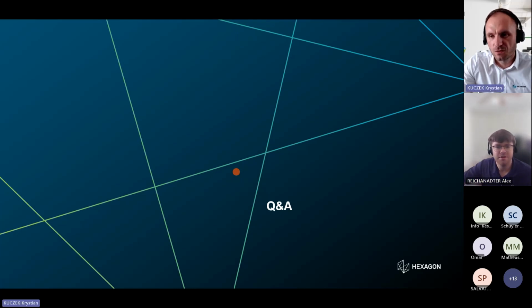If I would like to do it like you would like to have it, then I will go for a bushing representation where you can apply the 6 degrees of freedom model, including the stiffness. So the translational stiffness in X, Y, and Z direction, and the same rotational stiffness in the X, Y, Z direction, also including bushing property files. You can incorporate damping effect if you want, so not only the stiffness, and preload if needed. So I will go for a bushing element at this position.